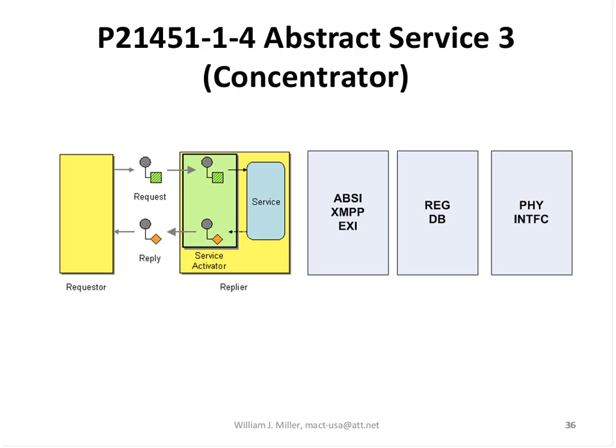This is a very important element, which I'm going to touch on in more depth here as we go further, and that's the idea of using a concentrator. XMPP has a XEP extension for being able to provide concentration of various sensors. So if you're collecting information, for example, from an OPC UA server, which was maybe collecting data from Modbus, Profinet, or other field devices, and you want to share that information to the cloud.